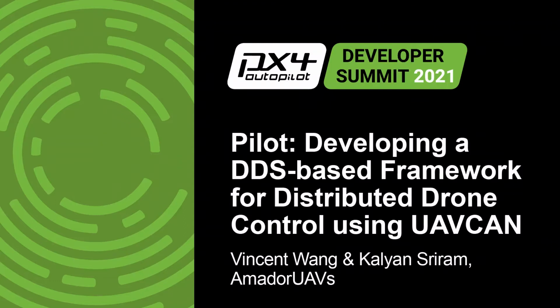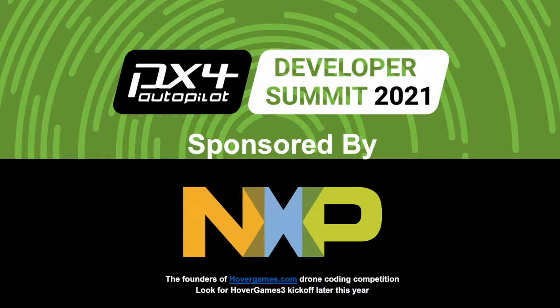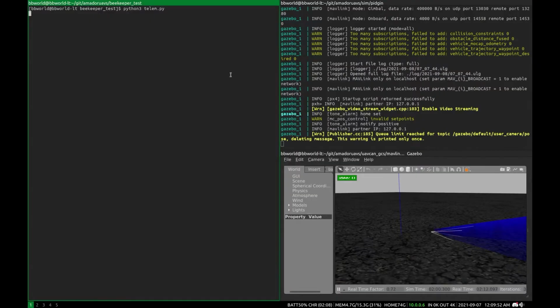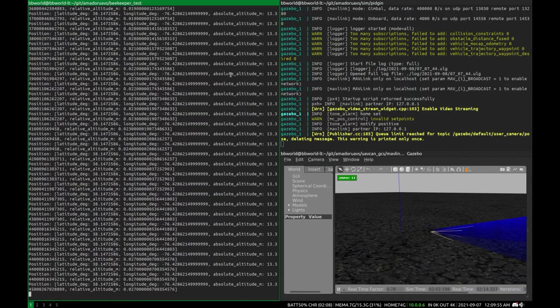In the process of building our team's ground control solution for the UAVSI SUAS drone competition, we ran into a number of design challenges. Our stack required multiple complex components to interact with the drone. For example, telemetry logging and path planning components, and other data connections for visualization and competition mission data. Considering these requirements, our team decided to experiment with using a data distribution system, or DDS, to integrate these services.